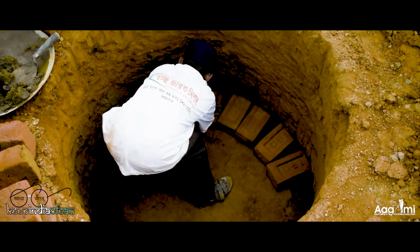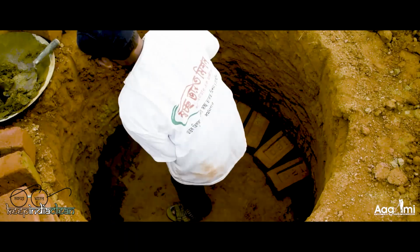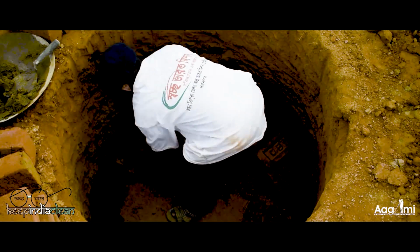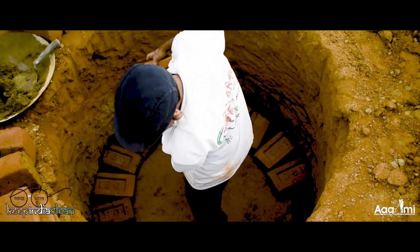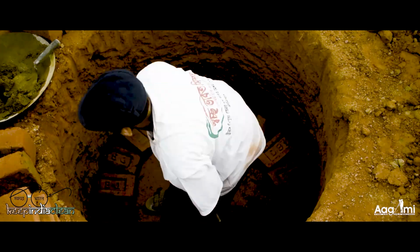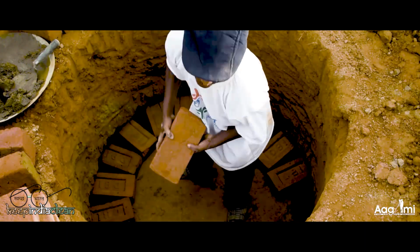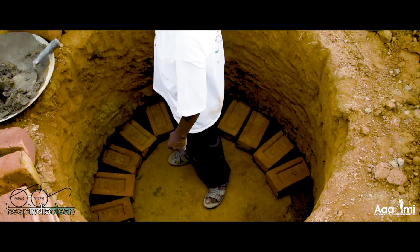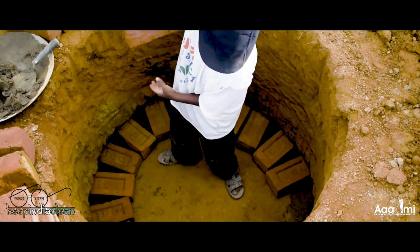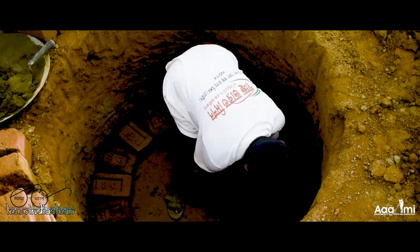Even the required amount of oxygen to convert the faeces into manure becomes less. The deeper the pits, the weaker the walls become, and they may fall down into the pit. Moreover, when the depth is more than 1 meter, the faeces may contaminate the underground water layer. Also, we should always keep a safe distance from the source of drinking water.